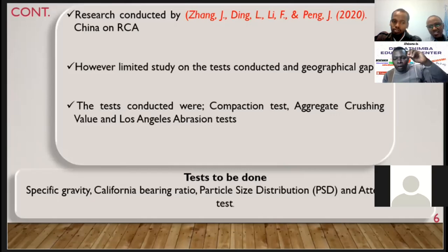In the rubble, like from buildings which have collapsed, I wanted you to investigate, because it's obvious the aggregates themselves have been recycled, used and investigated in concrete. Now I wanted to see the fines. The fines we are talking of are like 5 millimeter and below, or even 4.75 and below.